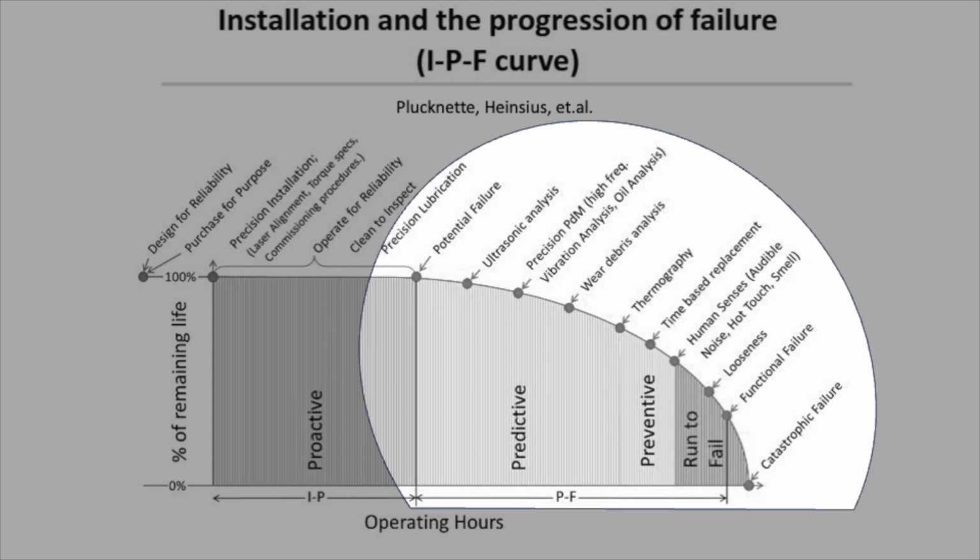Condition monitoring programs are only effective if the P to F interval is sufficiently long for planning, scheduling, and performing a corrective maintenance task to remove the potential failure from the system before it reaches functional failure. Effectiveness therefore depends on the planning and scheduling capabilities of the organization.